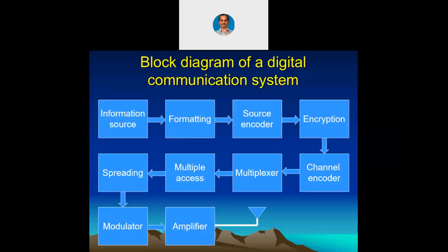It is possible by means of an allocation of frequency, an allocation of a time slot, or an allocation of a code. These are all beautiful techniques which were developed in the last few decades. In fact, it is because of CDMA that now we have 3G and 4G. In future, we will have 5G, basically because of a very innovative method called code division multiple access, where frequency can be the same, time can be the same, but for each user a specific code will be allocated.